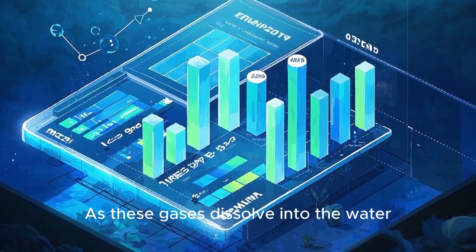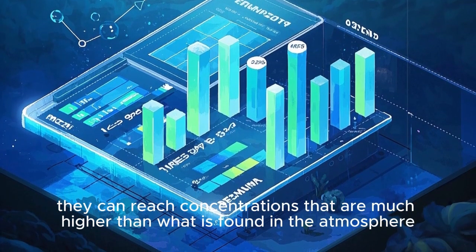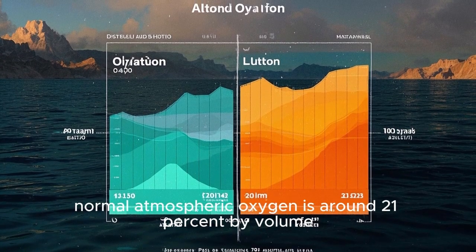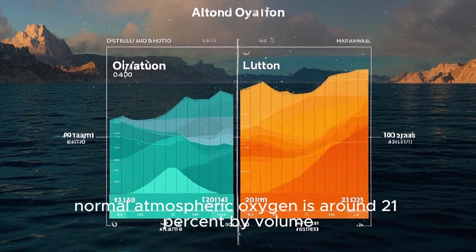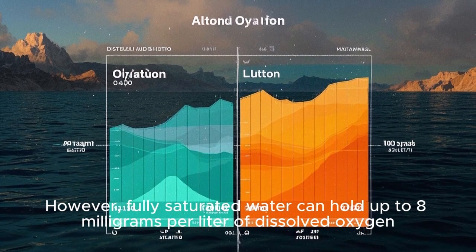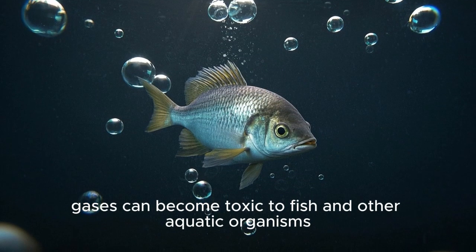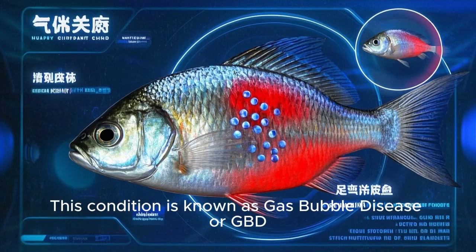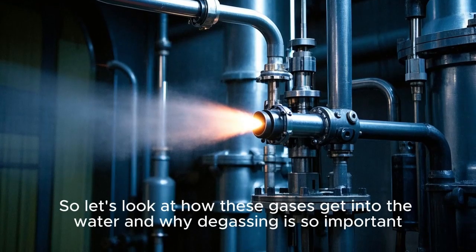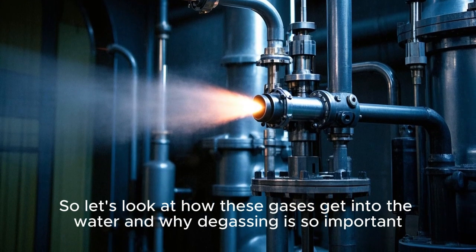As these gases dissolve into the water, they can reach concentrations that are much higher than what is found in the atmosphere. For example, normal atmospheric oxygen is around 21% by volume. However, fully saturated water can hold up to 8 milligrams per liter of dissolved oxygen. When this happens, gases can become toxic to fish and other aquatic organisms. This condition is known as gas bubble disease, or GBD. So let's look at how these gases get into the water and why degassing is so important.